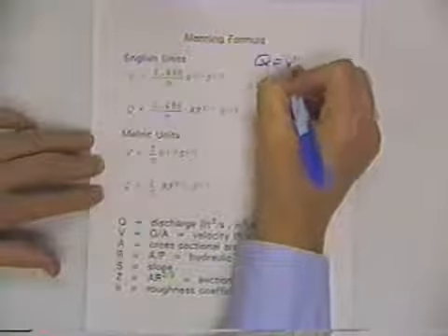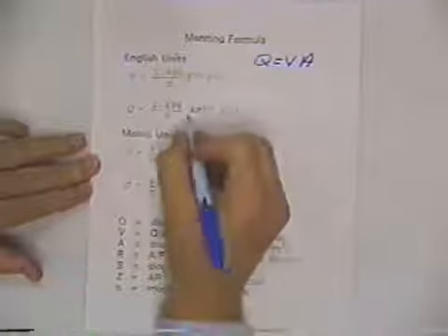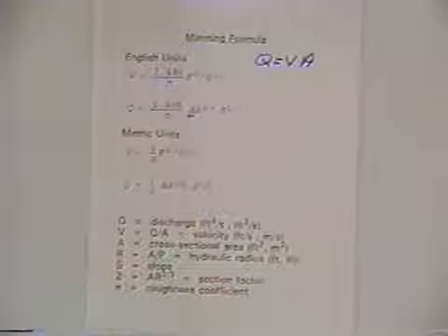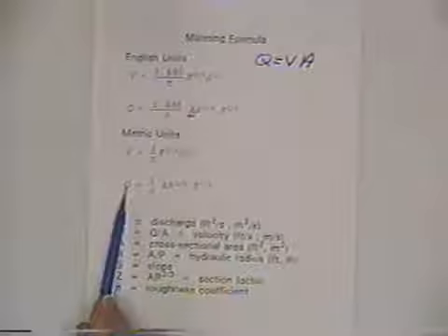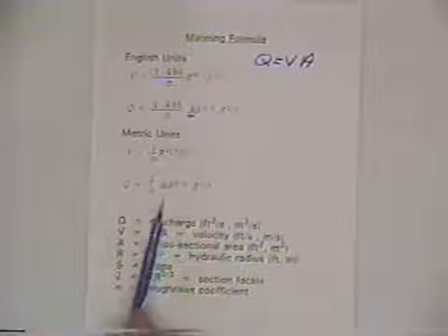And, well, the equation we're used to using is Q is velocity times area. And so if you multiply both sides by A, you put in an A there and an A there, you write the same equation in terms of Q. And so Q needs to be in cubic meters per second or cubic feet per second, the A in square meters or square feet, the hydraulic radius in either feet or meters, and of course the slope term has no dimensions. And so that's Manning's equation.